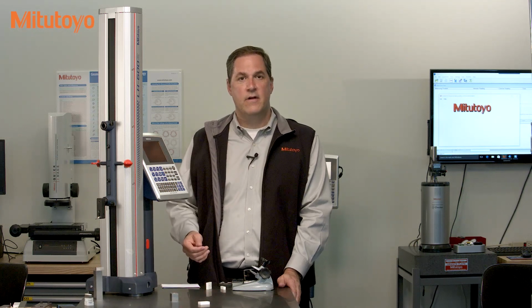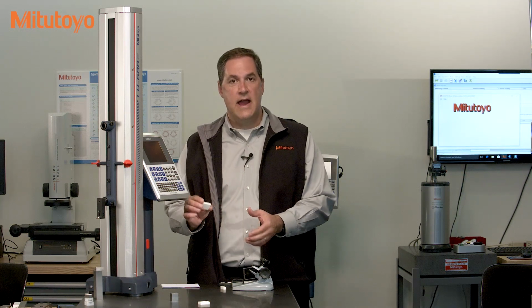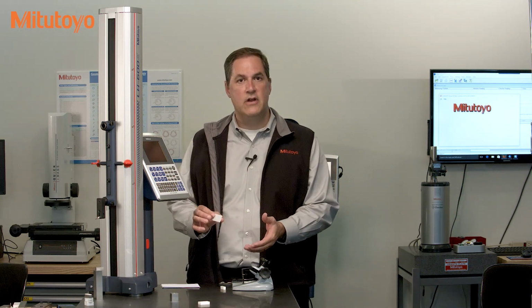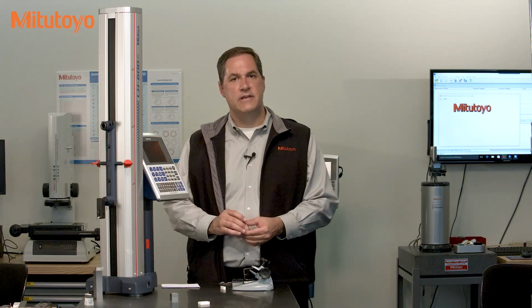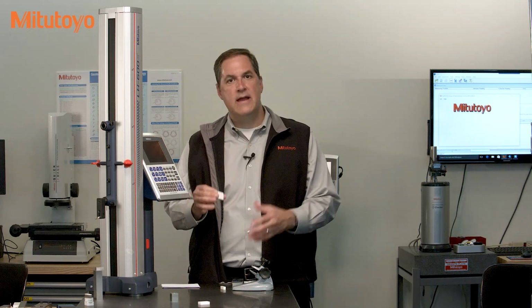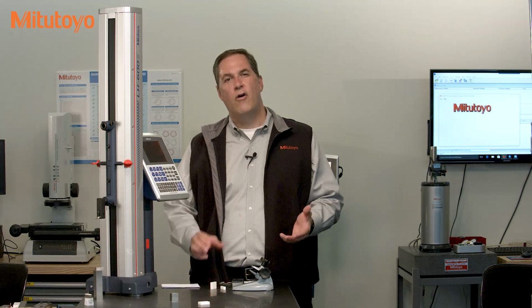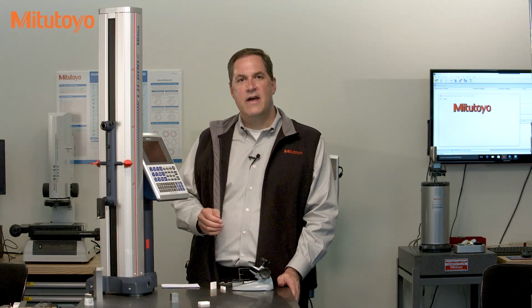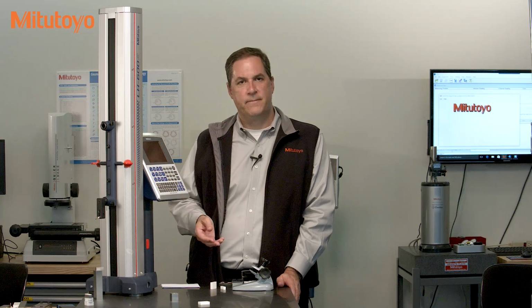And just like the imperfections of these gauge blocks and their calibrations can cause errors, so too does our inability to achieve a perfect 68 degrees Fahrenheit. Both the calibration of this gauge block and the temperature of the lab environment create errors. Or put a slightly different way, they can contribute to the uncertainty of the measurement.